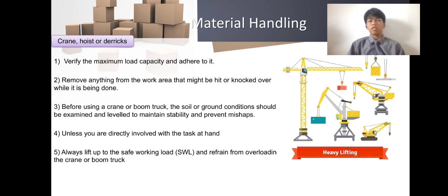Before using a crane or boom, the soil or ground condition should be examined and able to maintain stability and coordination. So before using the crane, make sure to check any particular hazard on the crane.